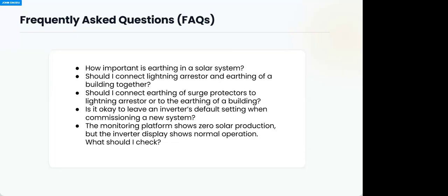So if they cannot tolerate it, that's why you have all those breakers that are properly rated around the inverter. If current flows through a wrong section and the current is excessive, the appropriate breaker will trip. That tells you something is wrong. And when that happens, you correct it. Maybe by then you now know, oh, it's because they have reversed the input. That's why this breaker tripped, because that's what's going to happen eventually.